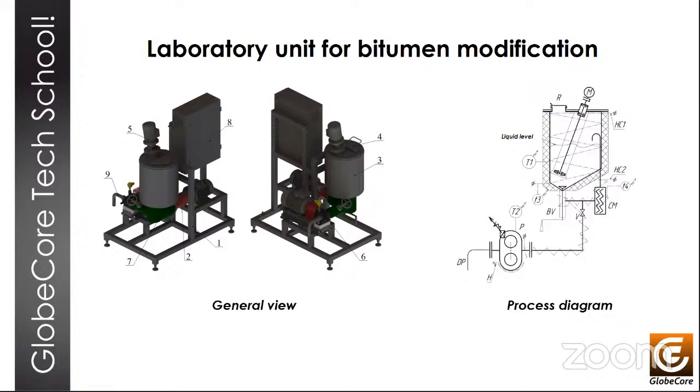The temperatures of bitumen and the surfaces of the components are monitored using temperature sensors, and these are displayed in the control cabinet in position 8. The components are driven by electric motors through elastic couplings.